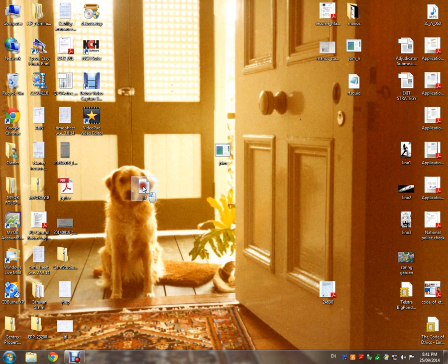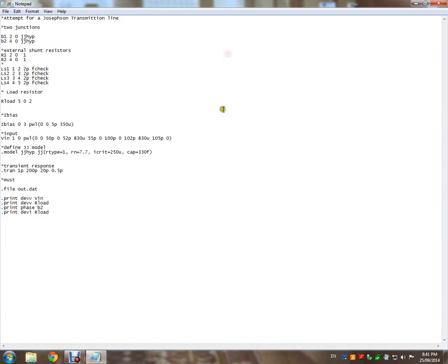Alright, let's continue this tutorial. As I showed you earlier, I'm going to code the circuit we saw. So, we use an asterisk to make a comment. Just put the asterisk at the beginning of the line. Don't put it in the middle, it won't work.